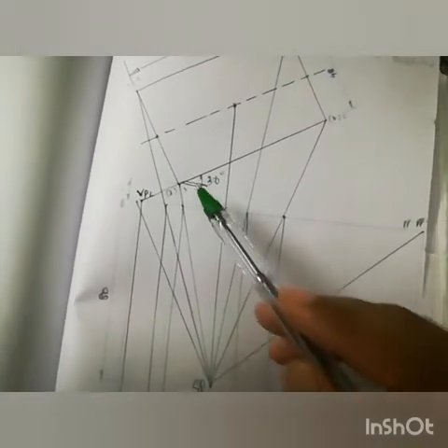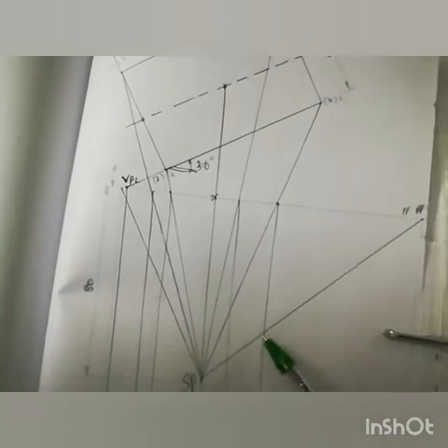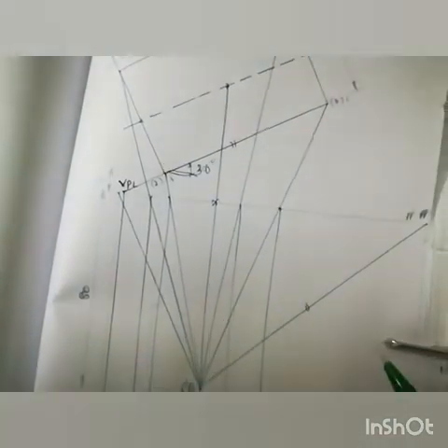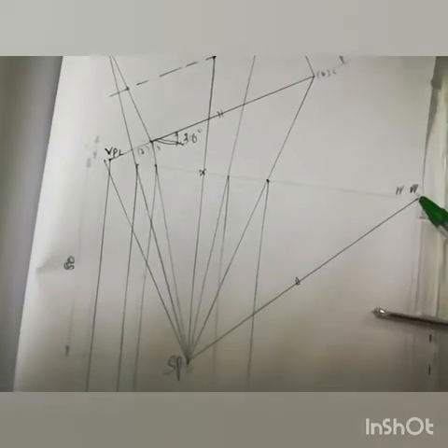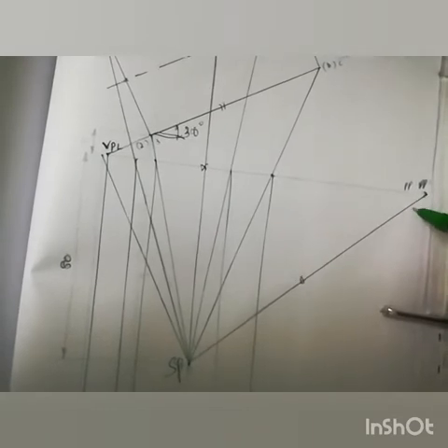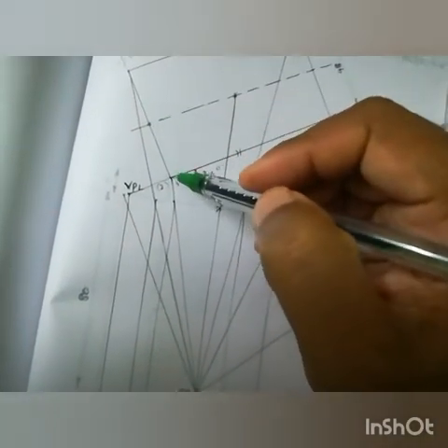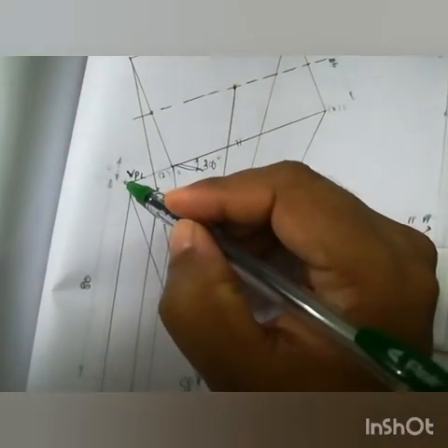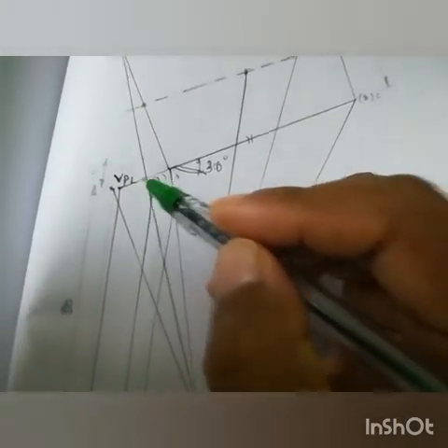So for that, draw a line from SP towards picture plane in such a way that this line is parallel to this edge. So if you draw a line parallel to this edge from SP to picture plane, that will be the vanishing point, right? So this point where this line meets the picture plane is called vanishing point right, VPR. Similarly, to this edge you can draw a parallel line from SP to the picture plane, so that this point is called vanishing point left, VPL.